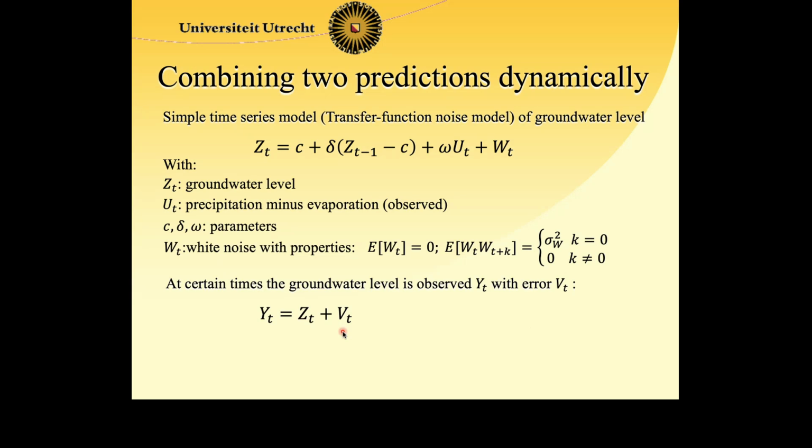That is when you hit the water table level, and then you measure from the tape what the depth of the water table is. That is how it's traditionally done, and then the error would be on the order of 1 to 2 millimeters, something like that. But even if you use a pressure transducer, you would have maybe half a centimeter measurement error.